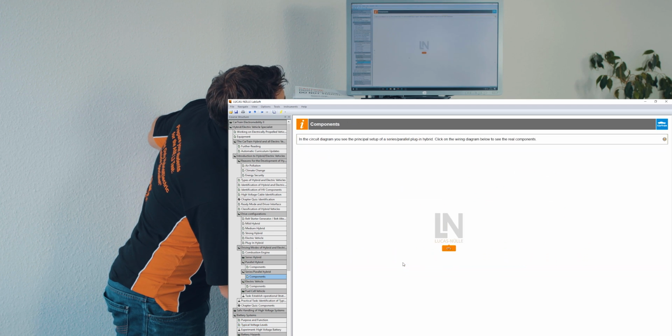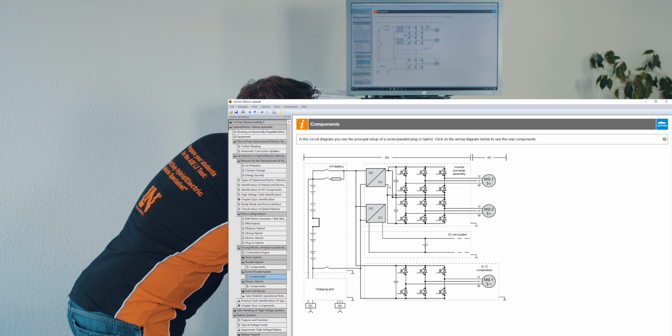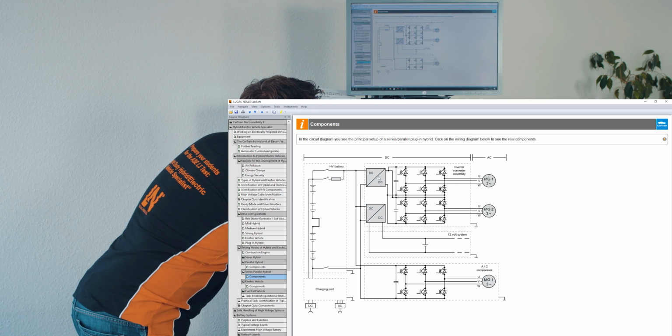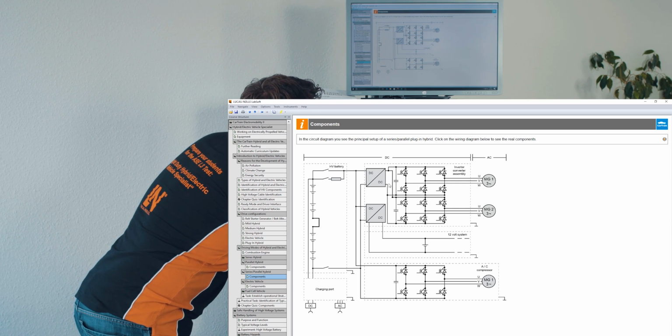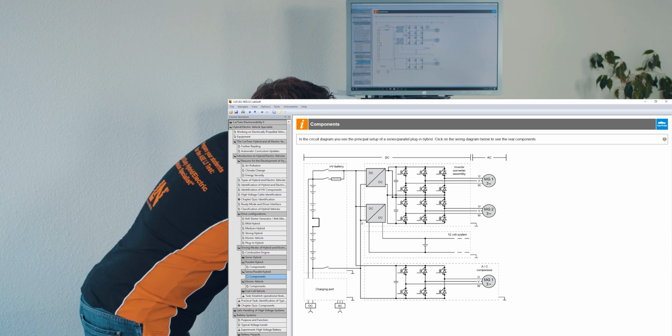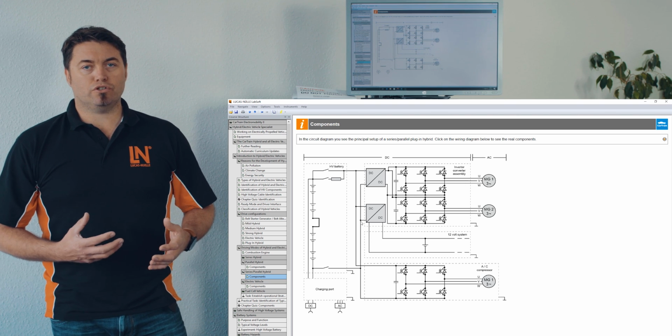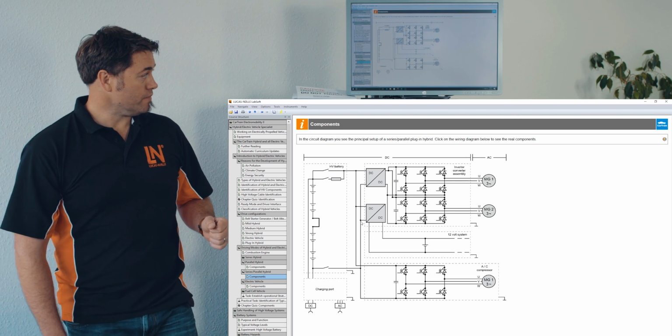Now, when we go back to this wiring diagram, with the two DC to DC converters that you see here, the top one is especially for the high voltage. We've got the high voltage coming in from the battery, and then this is converted to an even higher voltage for the traction motors, the traction motor. The lower one here is basically to replace our alternator and is used for charging the system.